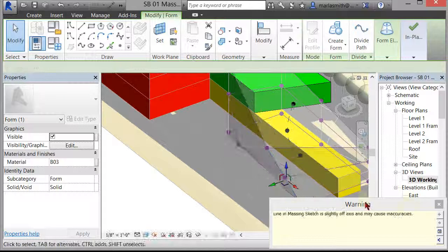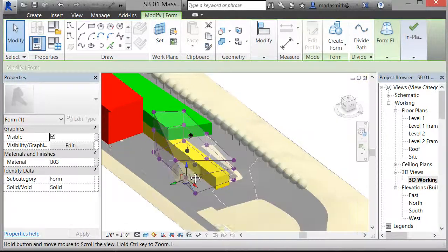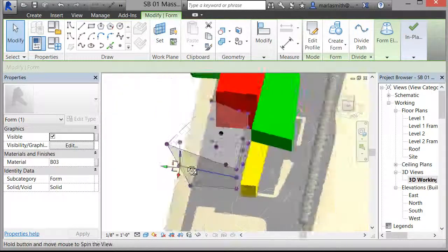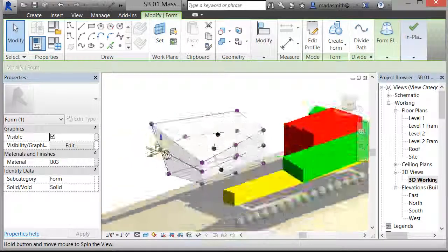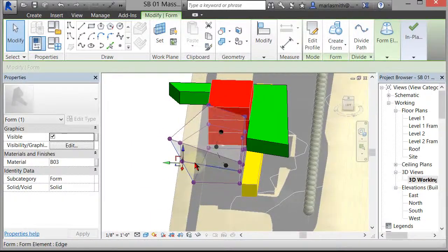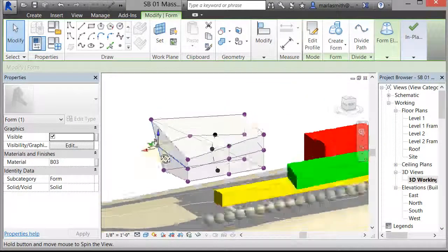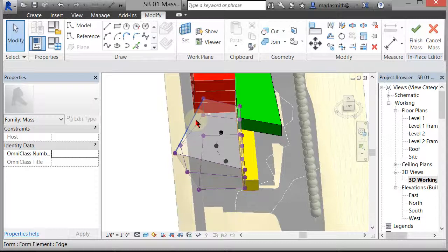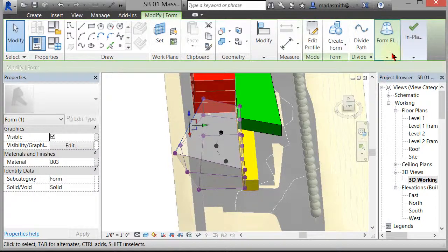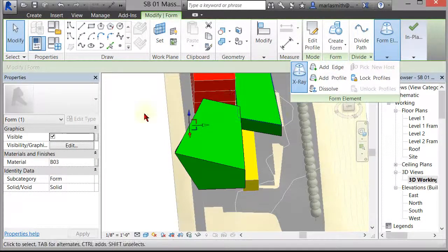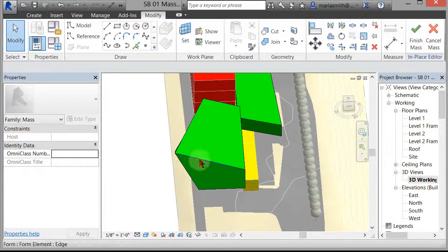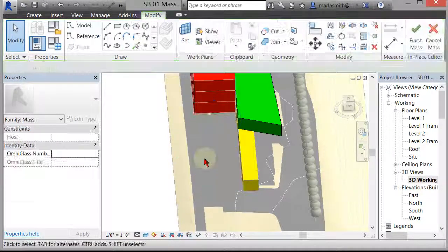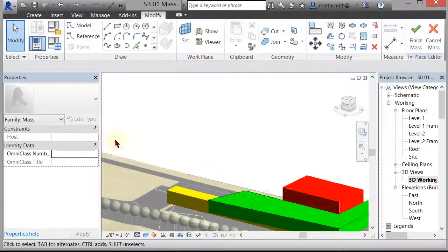So Revit is really showing you how it's generating that solid, right? It's going through and creating a series of profiles along a sweep, basically, right? So you can get complex very quickly. All right. So to get out of X-ray mode with these, it's just a toggle. So you pick it and click X-ray, and it goes back. So I'm going to tab select this guy and delete him because we're working with this.